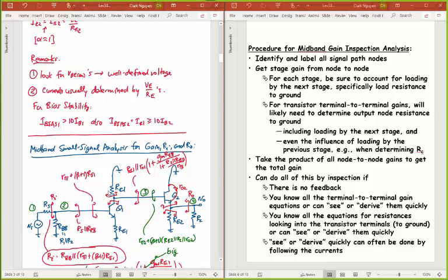If there is feedback, you can't do what I just did, because feedback sticks a whole wrench in there. If there is feedback, what you have to do is go back to the hybrid pi model, plug them in, and do that analysis. And it's going to take time, but it's the only way to handle something that has feedback in it. There are other better ways to handle feedback. That I guess what I said is not true. You don't have to go to hybrid pi, but those things you don't learn until the end of EE140, when you really start tackling feedback problems.